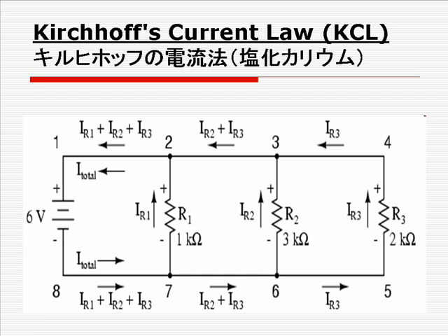But there's more going on in this circuit than just that. Taking a look at the currents at each wire junction point, or node, in the circuit, we should be able to see something else. At each node on the negative rail wire 8-7-6-5, we have current splitting off the main flow to each successive branch resistor. At each node on the positive rail, we have current merging together to form the main flow from each successive branch resistor.